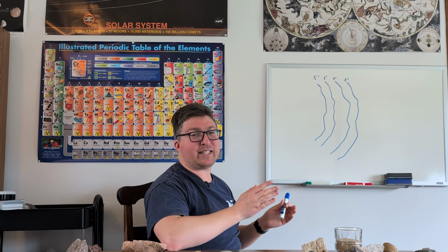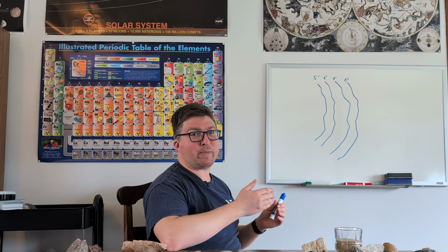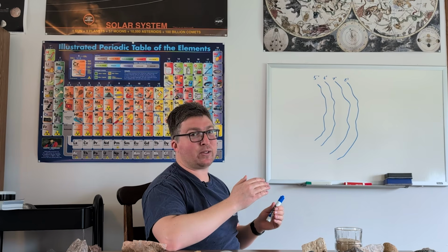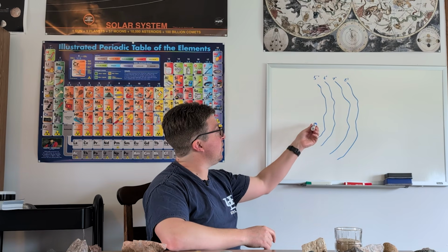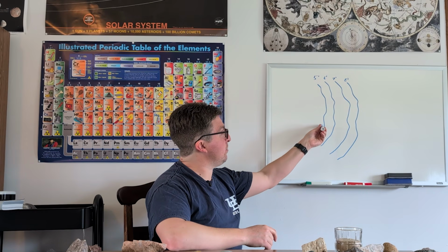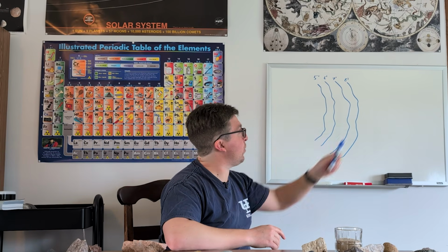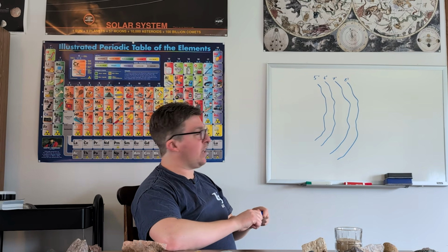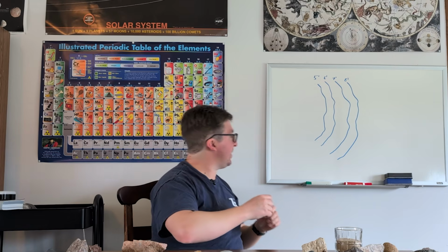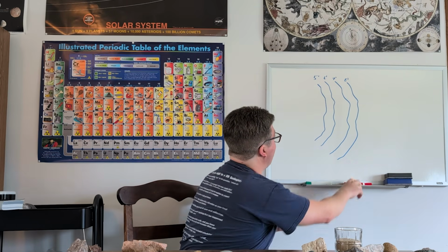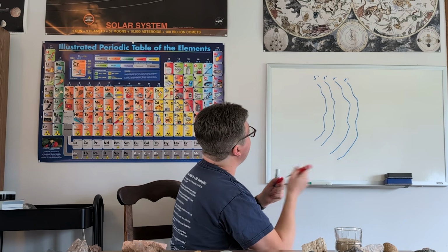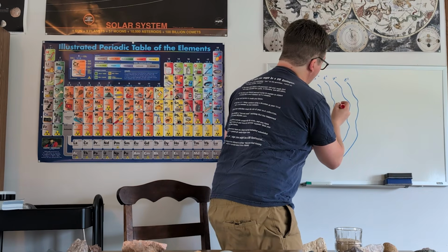It's exactly the same as a topographic map that shows the elevation of the ground surface, except now we're looking at the elevation, or rather the depth, of the groundwater surface of the water table. Now, if you place a well, let's say we'll put our well right here.